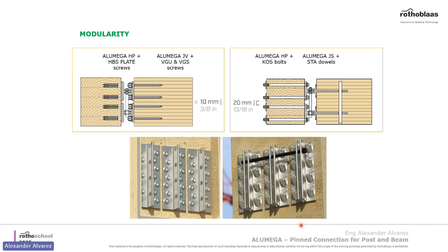And then here you can see, as I said before, maybe you have a bigger beam, you have a bigger load. Don't worry, you can also pair them up, up to three connectors. You can see here how you can go about it. We also have guidance on how to space them out between each side. We recommend about 3/8 of an inch from each other. And then you can see here there's a bolt. What you would do is slide up one of our bolts called the mega bolts. Like you see there's a rod right here.